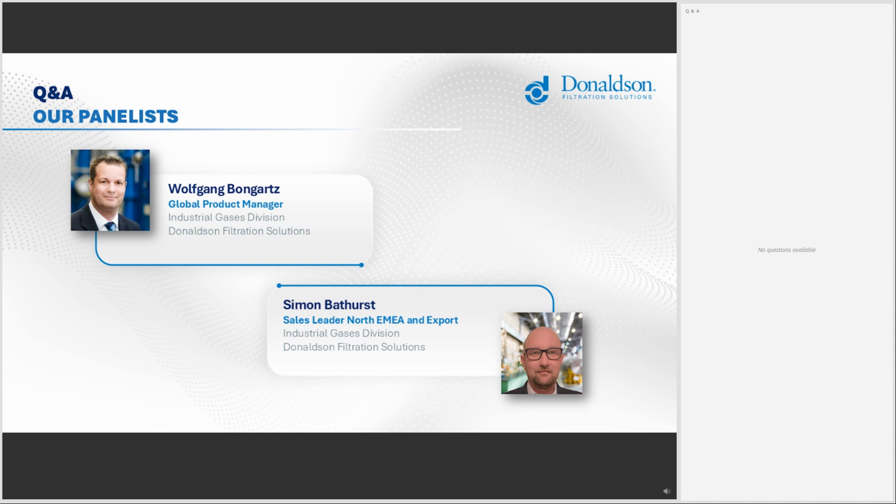Great. Thank you, Simon. Moving up to the next one. What type of filter media is recommended for applications requiring minus 70 degrees pressure dew point? Okay, this question is about filter media. So in the desiccant dryers we are talking about desiccants and adsorbents, and what we are using here is usually a kind of hygroscopic material, which can achieve dew points down to minus 70 degrees Celsius.